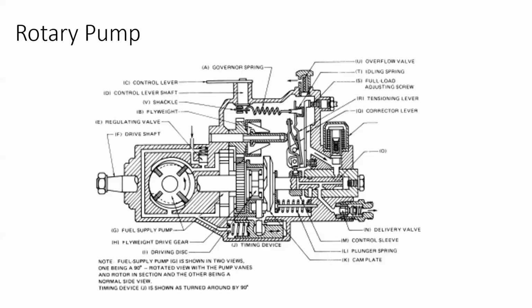I know this is not the clearest image, but let me try to explain as much as possible. Okay, so fuel comes here, right? Again, this is also filled with fuel. Inside of that, there are two sections. One section is over here, where it has a rotary pump which pumps the fuel from the fuel tank into the injector pump, right?